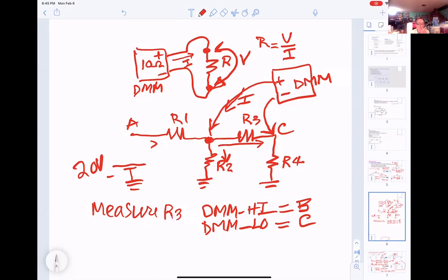In this case, normally you can use the color code if you want. Or you can test with the voltage. If you get a wrong voltage value, then something is wrong with either R3, R2, R4, or R1. But taking a resistance measurement is not the way.